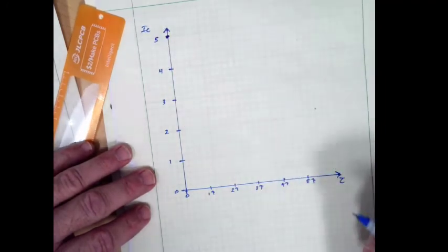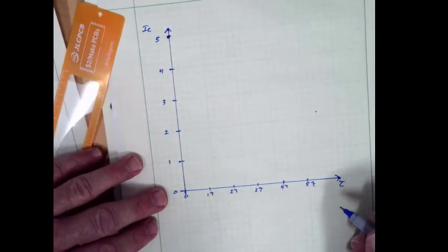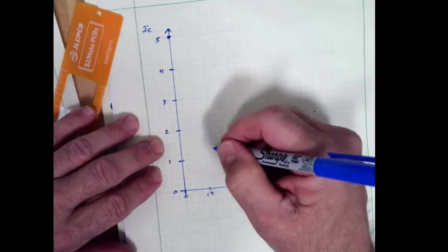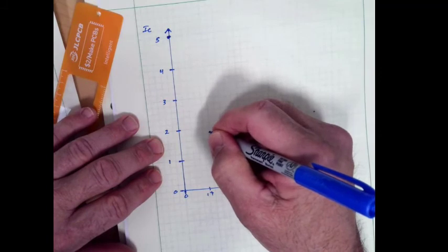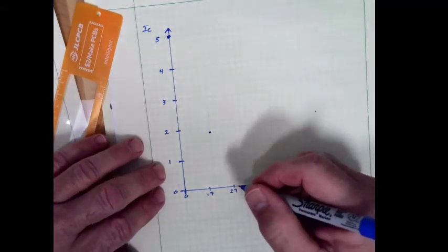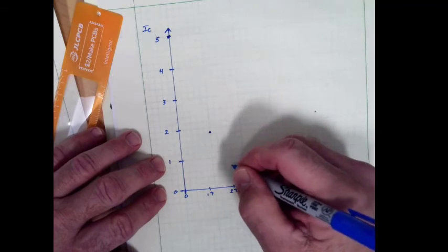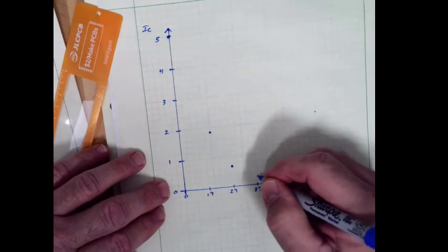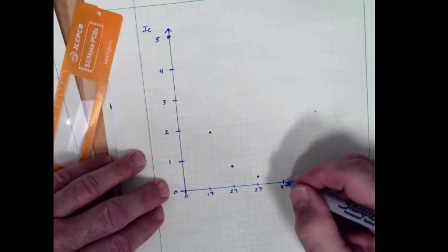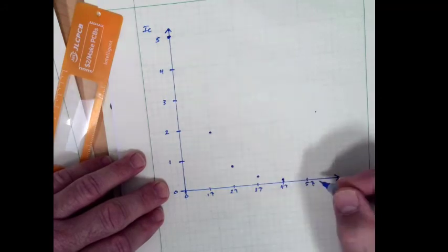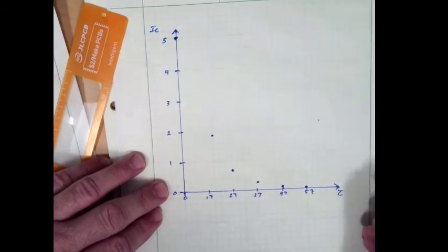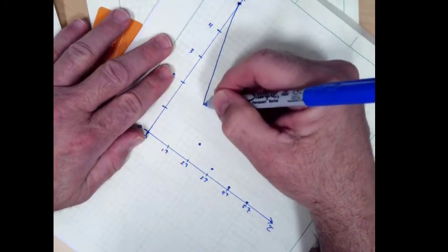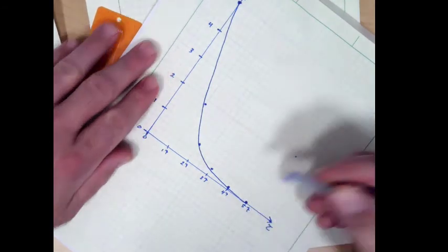So at time 0, we started off at 5 amps. At time 1 tau, we're at 1.84. So that's 2, 4, 6, 8. So a little bit up there. And at 2 tau, we're at 0.68. 2, 4, 6, 7, right around there. 3 tau, 0.25. So something like that. 4 tau, 0.18. So getting close there and just above the line right there. So we've got, you know, an exponential curve dropping something like that.